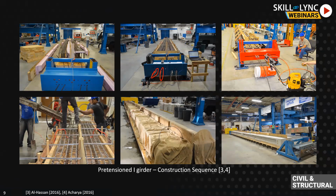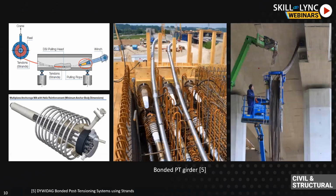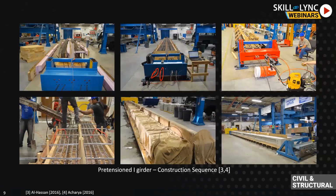So before we pour the concrete, we pull these strands. How do we pull these strands? Using a hydraulic jack. We calculate all those things, and we know exactly how much force we want to pull, and it's very precise. It can be in decimals of a pound or decimals of a kg. So we pull this very precisely, and when we pull, we use these anchors to hold that force. We keep holding that force, and while those strands are being pulled, we pour the concrete.